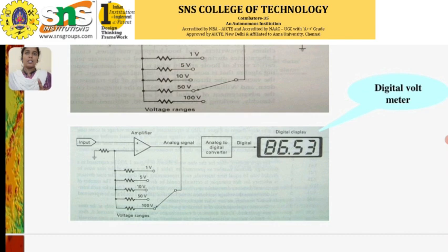Another one is the simplified design process of digital circuits, with flexibility and functionality. Digital circuits are easier to design using standardized components like logic gates, microprocessors, and design software, reducing development time. They offer flexibility as a single digital chip can perform multiple tasks by reconfiguring its logic. For example, a digital signal processor can handle audio, video, or sensor data with the same hardware, unlike analog circuits, which often require dedicated components for each function.